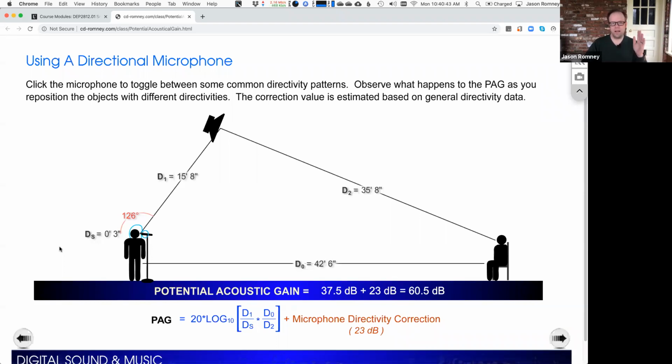And so I can sometimes get a bit more bang for my buck out of these directional microphones by filtering out those low frequencies, because I don't need them. I'm not trying to pick those up. So there's no point in trying to amplify them because all that's going to do is destroy my gain before feedback. So that's the one scenario where I think using an EQ could be helpful, is just using high pass filters on these microphones to filter out those omnidirectional frequencies. That way you can leverage this directivity as much as possible.